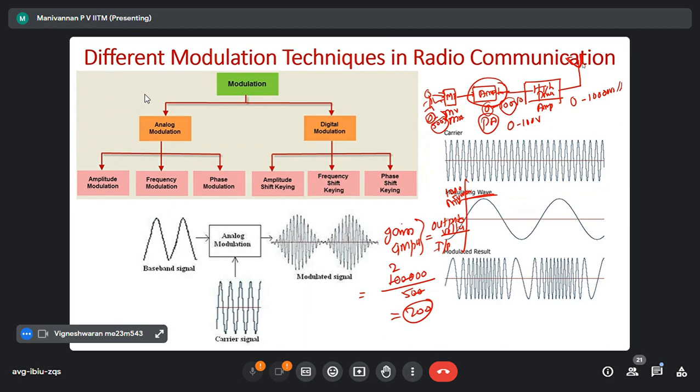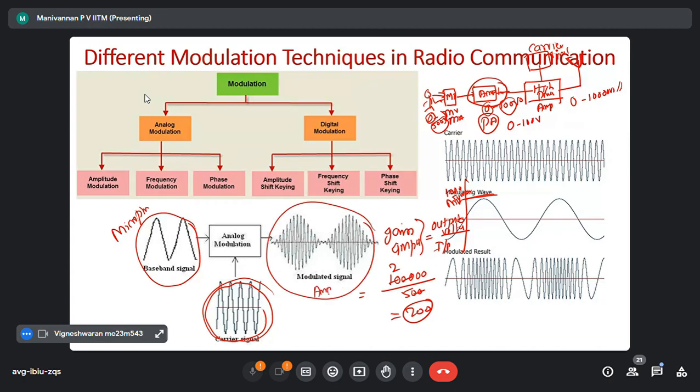But before giving it to the antenna, what they do is they add one more signal, what we call a carrier signal. In the power amplifier, they add the carrier signal. That's what this is. Please see here, I am circling. The carrier signal will be mixed with this signal, the audio signal from the microphone, for example. A single frequency component will be added to this. Then the output will be an amplitude modulated signal. Already we saw this amplitude modulated signal. That signal is given here. The AM signal, modulated signal, is transmitted as a wireless signal using a big antenna.